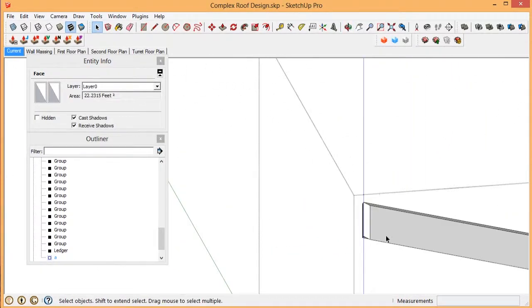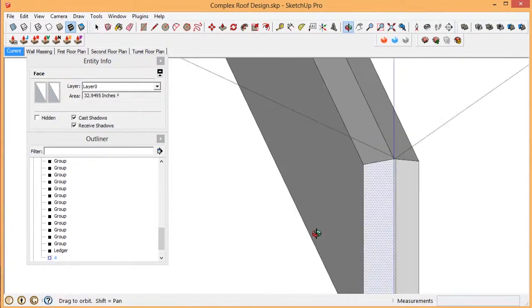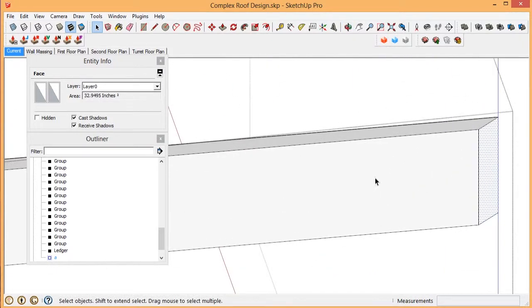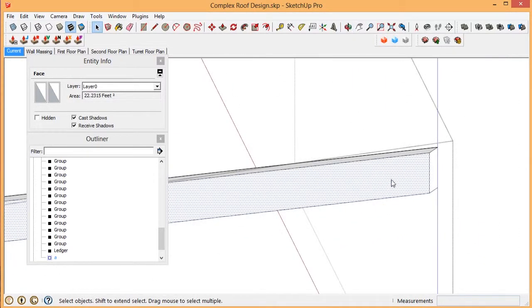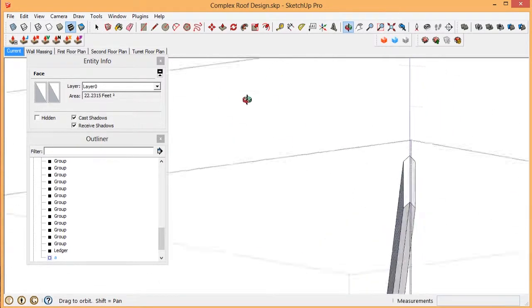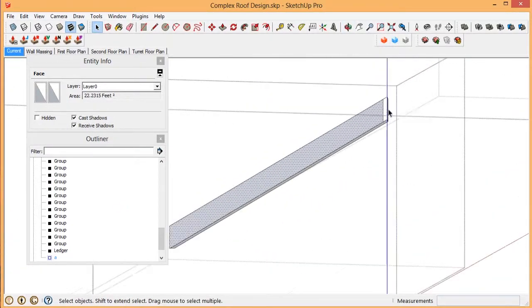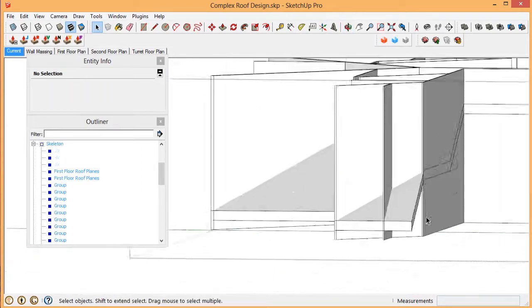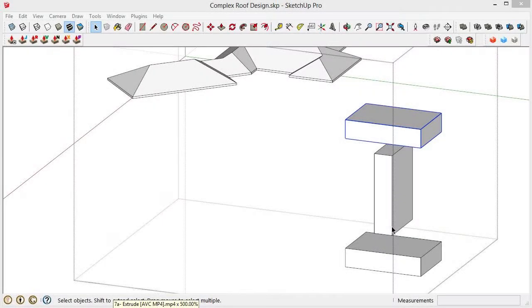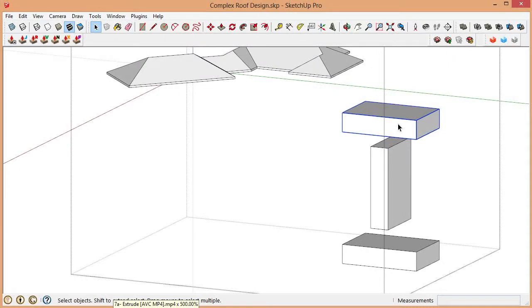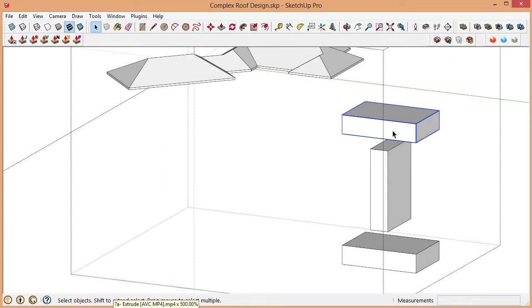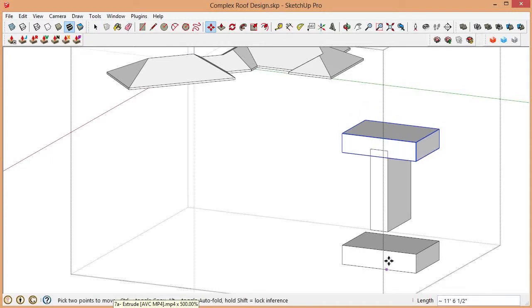Then of course good housekeeping is making sure that there are no reverse faces. In this case we'll select a face we know is not reversed, and then context, click, and select Orient Faces to make sure that everything has an appropriate face. Let's go over the trim tool real quick. I have 3 rectangles. I want to trim the middle rectangle so that it lies between the upper and lower rectangles. So I'll lower the upper rectangle a little bit so it overlaps, and likewise the lower rectangle.